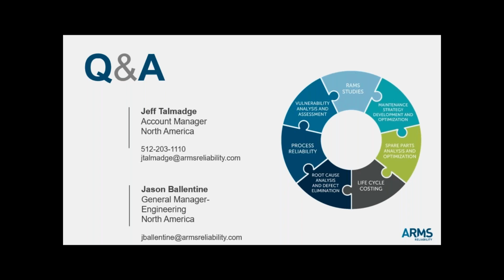I would do a full RCM type review because that enables me to really understand operating context. It allows me to do the justification that I need to change maybe the current philosophy that I have around those assets. It allows me to understand risk, to communicate that risk or that residual risk, and to understand where I need to maybe make a change that's outside of the strategy itself. So there's a number of reasons why that makes sense to do the detailed analysis on the high critical.